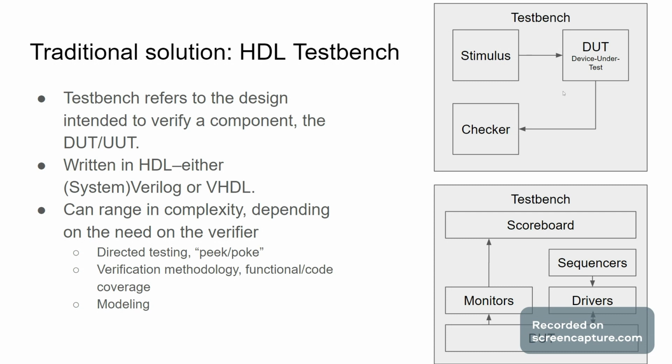And for a lot of engineers, that's good enough. Let's just build the thing and then run it on some test hardware. You can still learn a lot just by doing something as simple as that. And obviously it doesn't take any time really to build a simple peek and poke test bench. But on the other end of the spectrum, you might have a UVM.